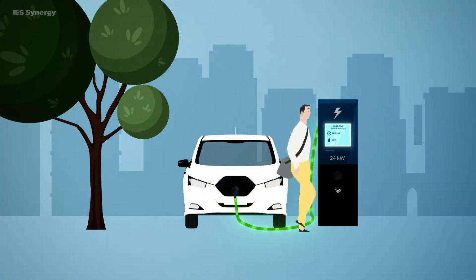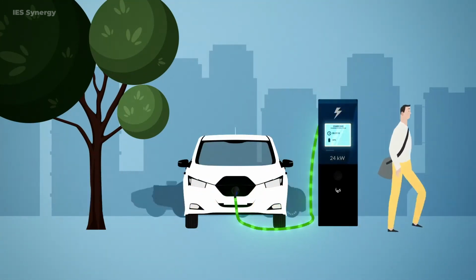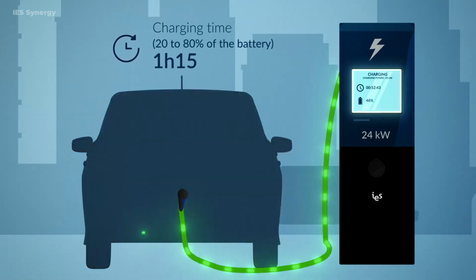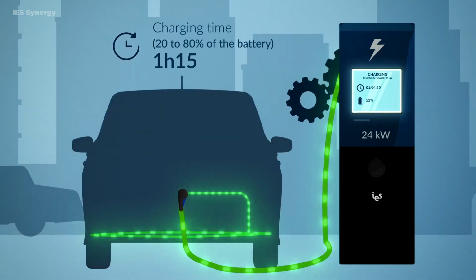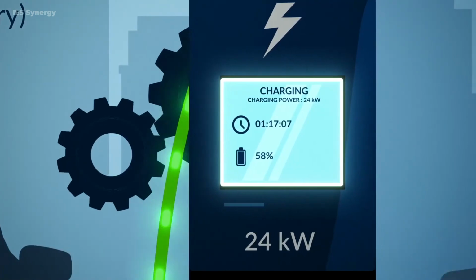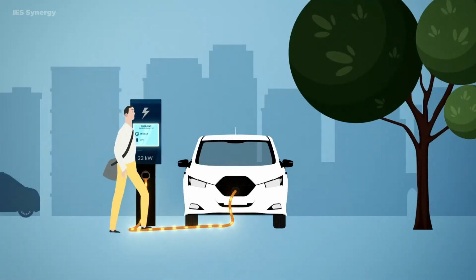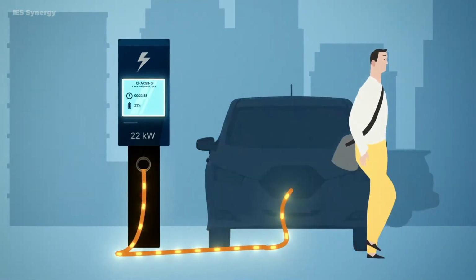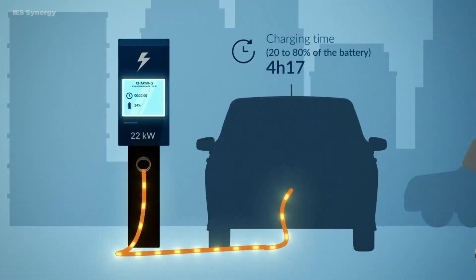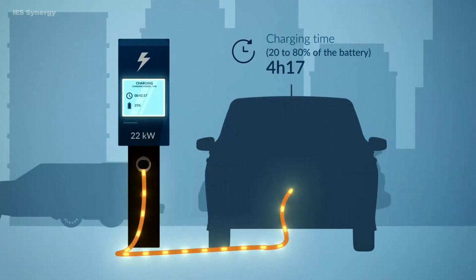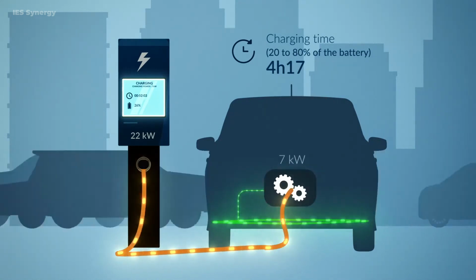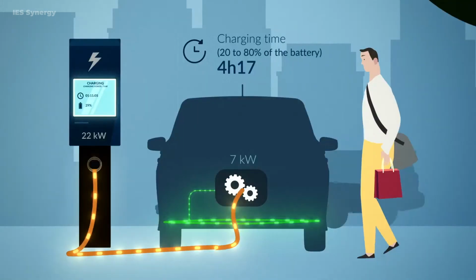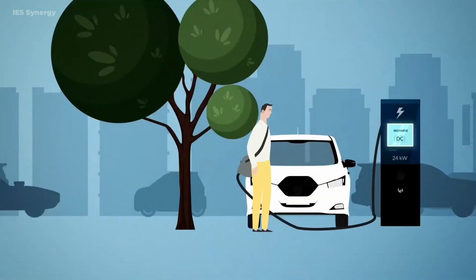The DC chargers are usually bigger since the converter is inside the charging station. This means that it is faster than the AC chargers when it comes to charging the battery. By contrast, if you use AC charging, the converting process only starts inside of the car. Electric vehicles have a built-in AC-DC converter called an onboard charger that converts AC power to DC power. After converting the power, the car's battery is charged.